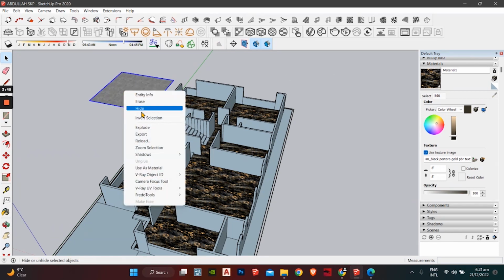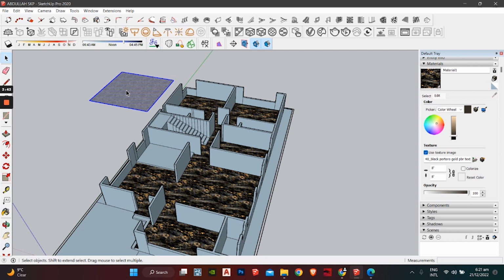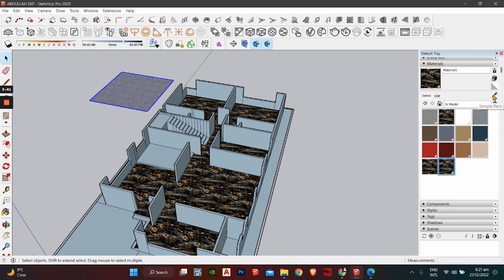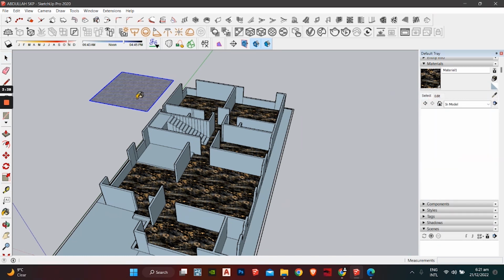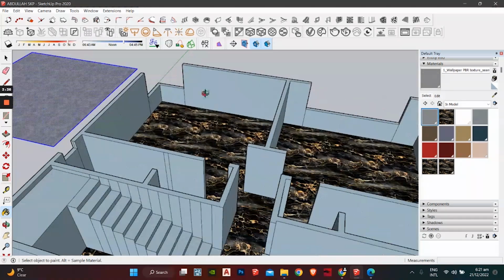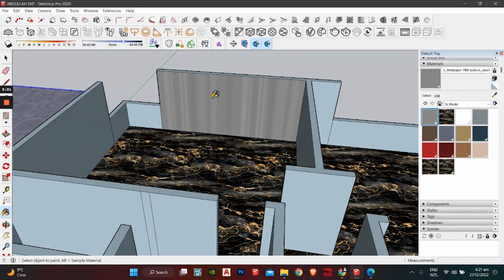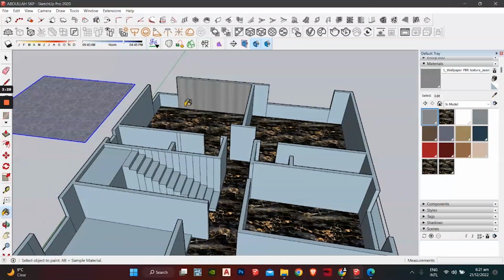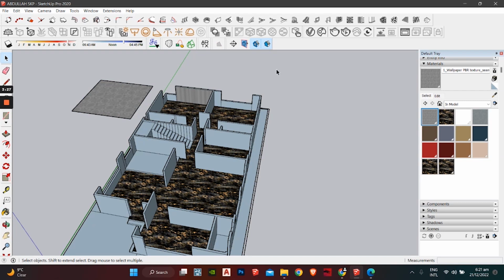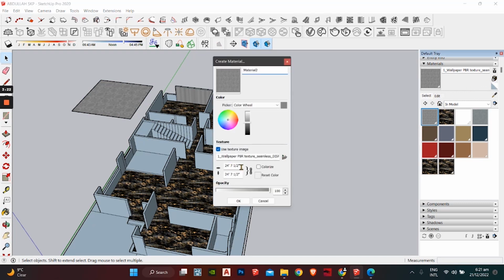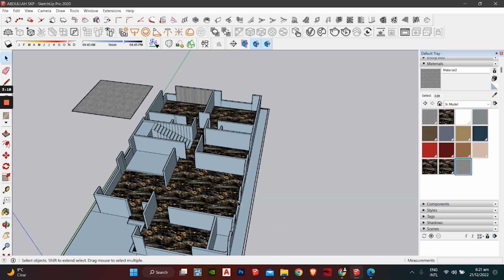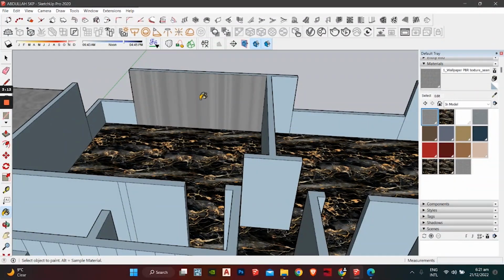We will right click, explode, going to select, and let's just use this wall. Okay, see how it doesn't match, how it's all distorted? This is how you fix this problem. Okay, you go into create material. Okay, this is 20, just change it. 10 by 10 seems fine. Enter, and once you get there, select, enter.